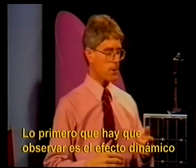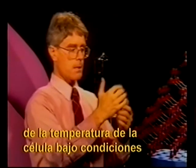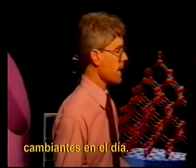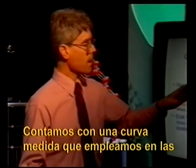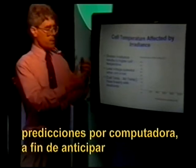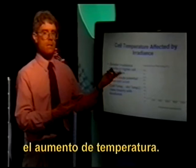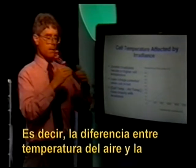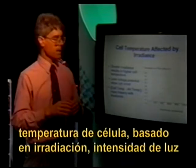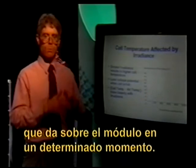One of the first things that we have to look at is the dynamic effect of cell temperature under changing conditions in the day. We actually have a measured curve that we use in our computer predictions to predict the temperature rise. In other words, the difference between air temperature and cell temperature based on irradiance, the intensity of light falling on the module at any one moment.